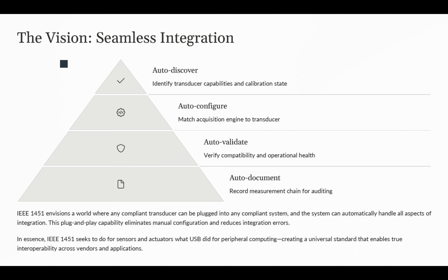They could auto configure to the system, so it basically matches acquisition engines to the transducer. They could auto validate their compatibility, and basically make sure that they are working in a healthy operational situation. And they could auto document, so they could log and record every data and measurement chain for possible future auditing.